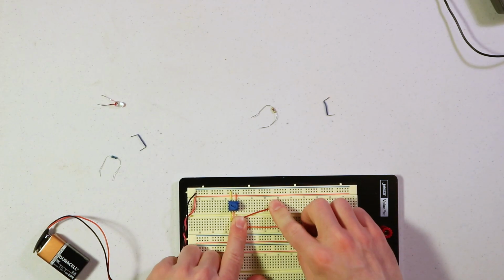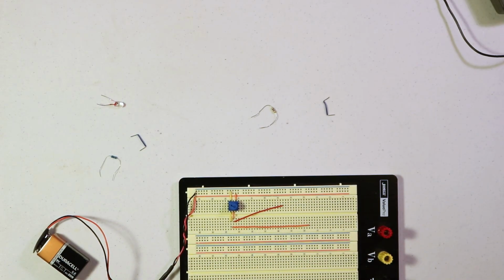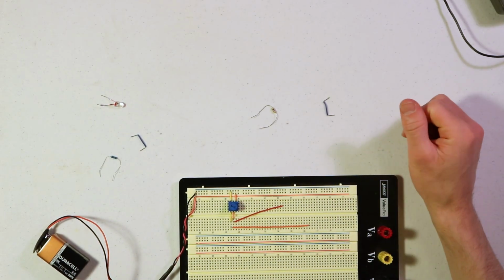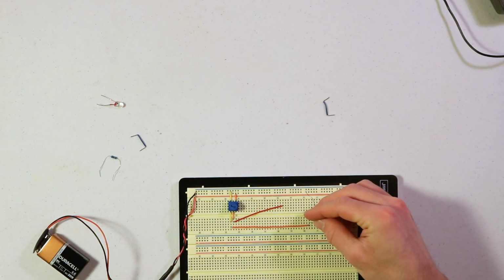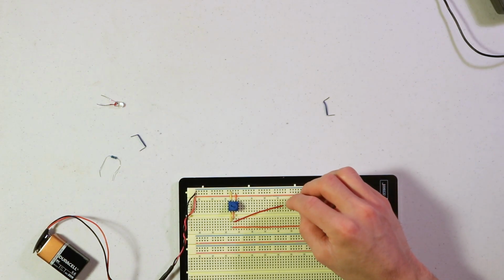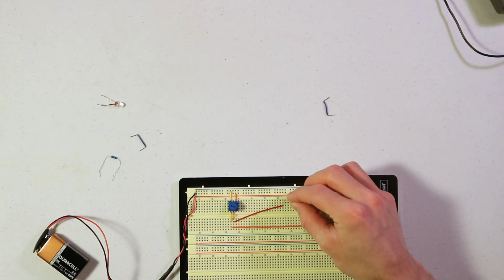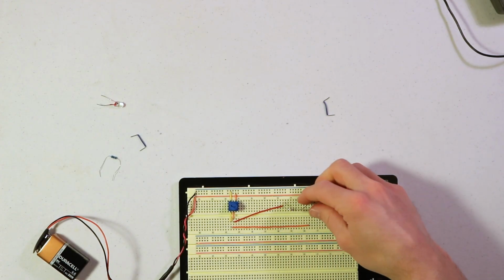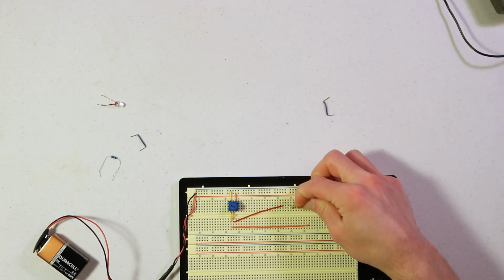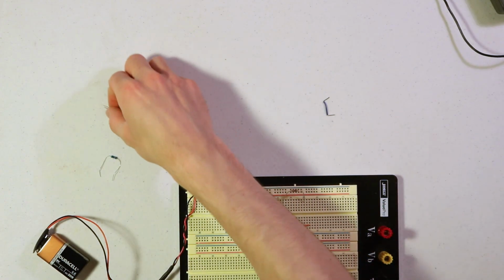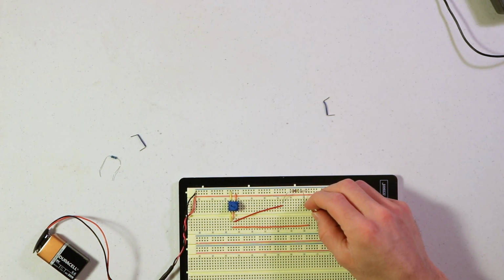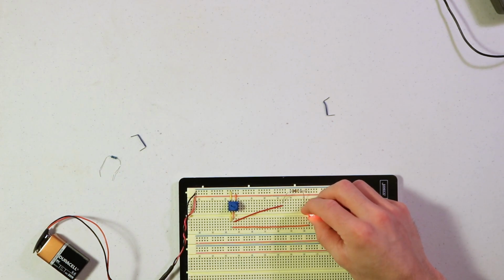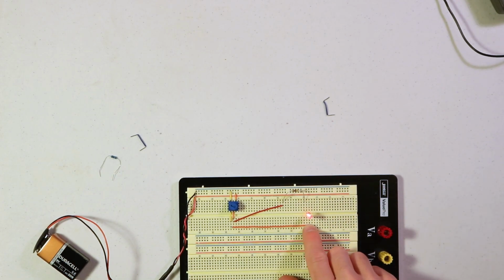And now what we're going to do is use this as our control voltage, our adjustable voltage to control the LEDs. So grab the 470 ohm resistor and just put that one in here, so that it's connected then to this red wire for me. It'll probably be a different color for you. Just plug that in there and then take your LED and attach that so that it goes from the resistor back over here to this line.